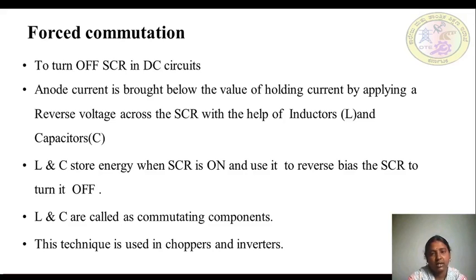These inductors and capacitors store energy when connected in the circuit and current is flowing through them. That is, when connected in the circuit along with the SCR, they store energy when the SCR is in the on state, and this energy is utilized to reverse bias the SCR, bringing the anode current below the holding current and making the SCR go into the off state.